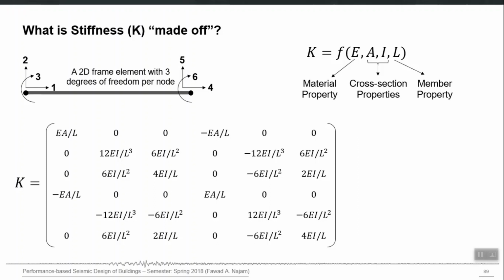First you have materials. Just consider any finite element program and the process of how you construct a computer model. It follows exactly that hierarchy, that you start with defining material properties. Those material properties are called in while defining the cross-sectional properties. So when you are defining a cross-section, you tell the program that this cross-section should be associated with that material, right?